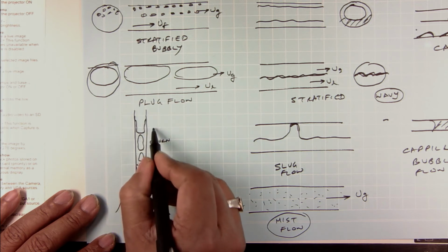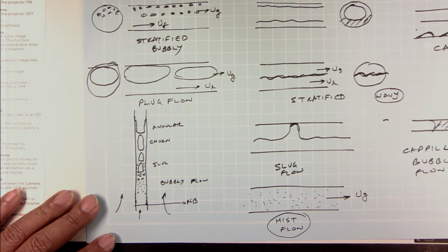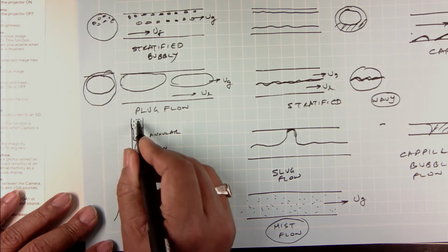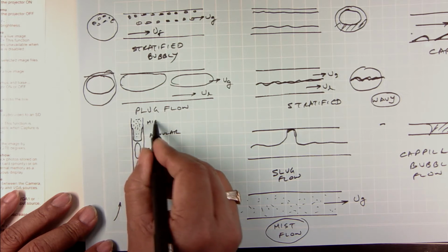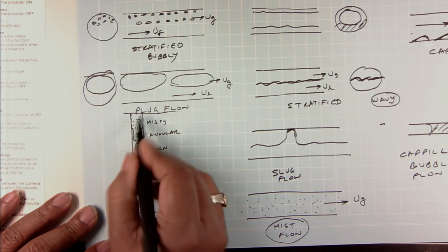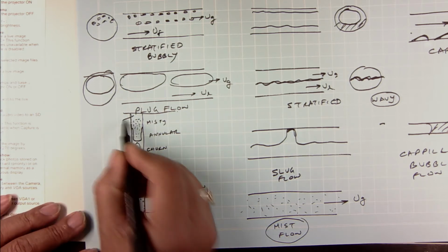Okay. So, you get into your annular flow, and then because of Helmholtz instability, you have entrained some of the droplets out, and so you are going to get misty flow, and finally, if your design is done right, all this mist will evaporate, and then you will have pure vapor flow.